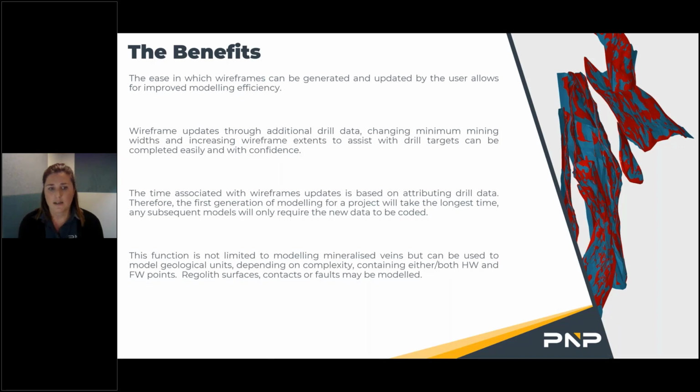And if you needed to add additional drill data, change your minimum mining widths based on different mining methodologies, or increase the extent of your wireframe to assist with drill targets, this could be done quite quickly. The time associated with this is really based on attributing data. The wireframing time takes no time at all.